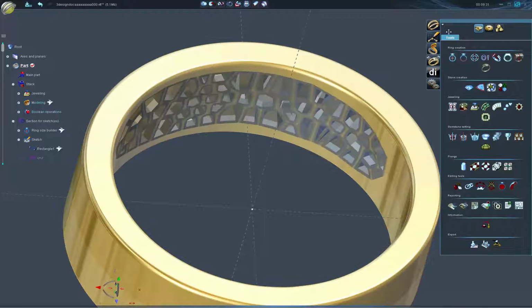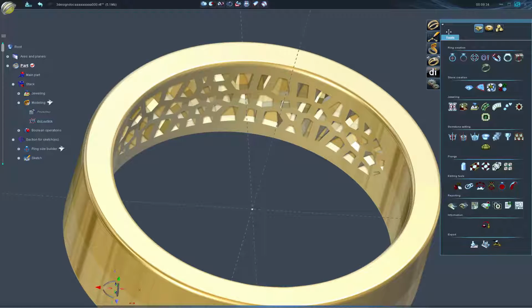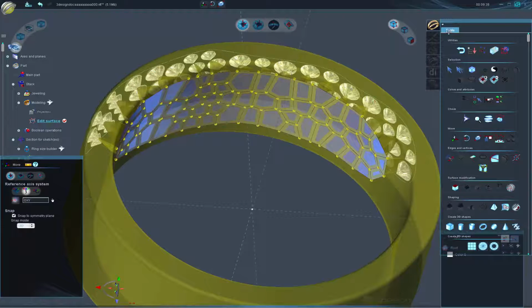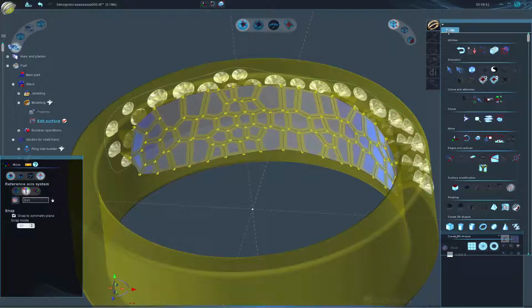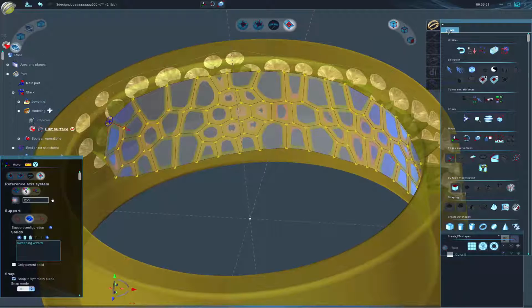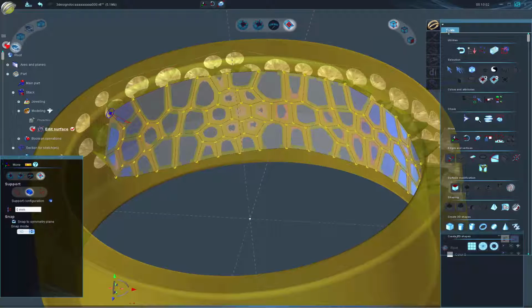If you are not using retopo, let's go back into that mesh. You will be brought into using the move tool. With the move tool, we want to use the fourth option, which is move according to a support object. And it's already selected because of the import option. And now instead of just sliding it around easily with retopo, you have your handle that you can move it around. You can see it's not as smooth. It takes a little more nudging to get things right. You got to be careful because you can also move in the Z direction. But definitely still workable.